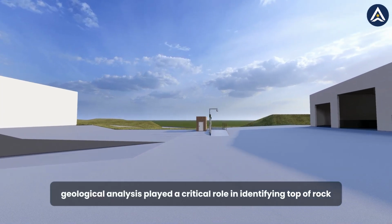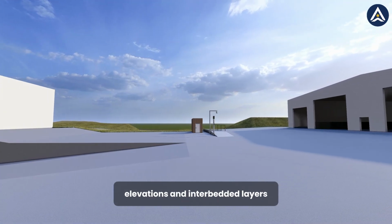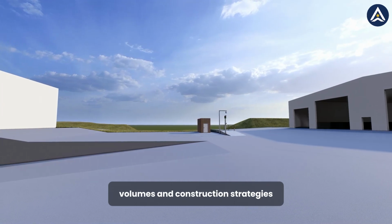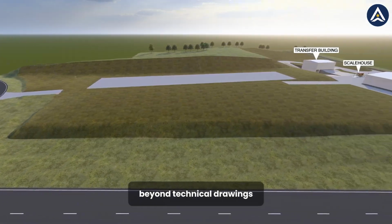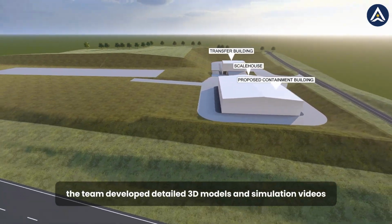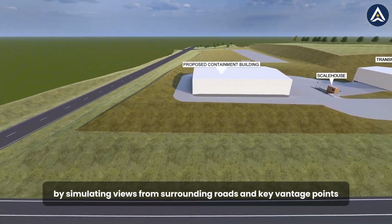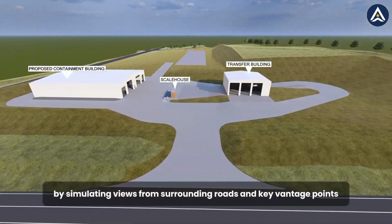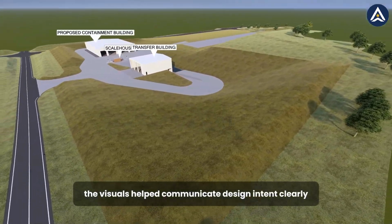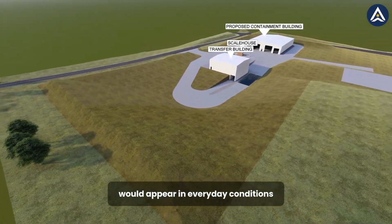Geological analysis played a critical role in identifying top-of-rock elevations and interbedded layers, which directly influenced excavation volumes and construction strategies. Beyond technical drawings, the team developed detailed 3D models and simulation videos that placed the project within its real-world context. By simulating views from surrounding roads and key vantage points, the visuals helped communicate design intent clearly, allowing stakeholders to understand how the facility would appear in everyday conditions.